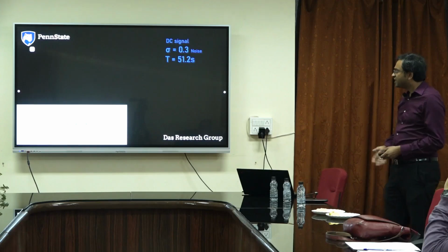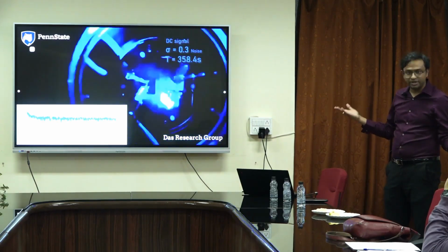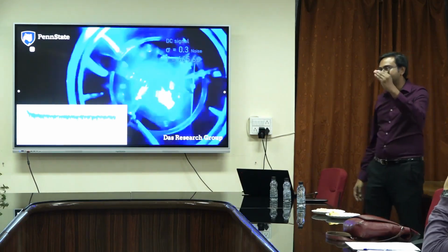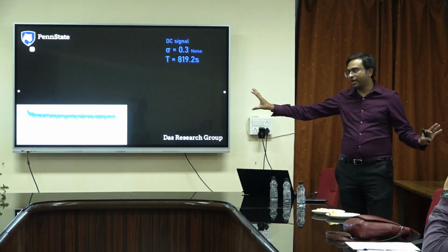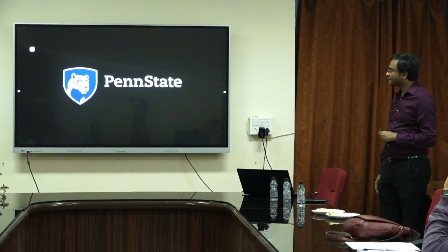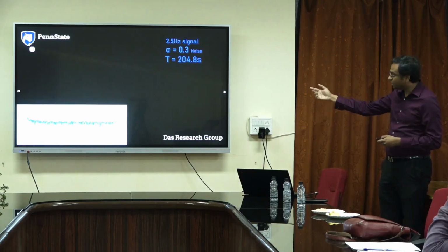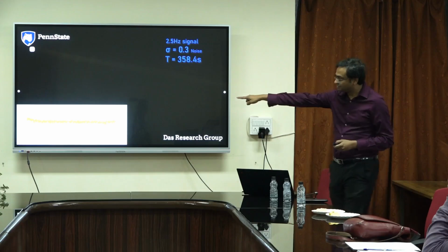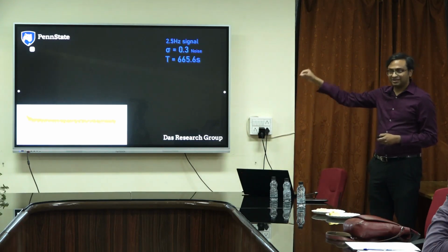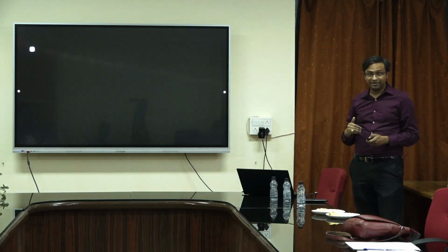Now if I take just a random LED source, it's just randomly glowing. No signal, because there is no particular frequency. It is just random, so nothing happens, only the noise floor keeps increasing. So the signal which is very weak is not detectable, and if it is noise, there is no signal. What if I combine the two? That is the last experiment. If I combine the two, now there is a periodic signal in the background, the small one, and there is some noise. And you see the peaks get detected. So this is an experimental demonstration of stochastic resonance to enhance the detection limit of our photodetector.